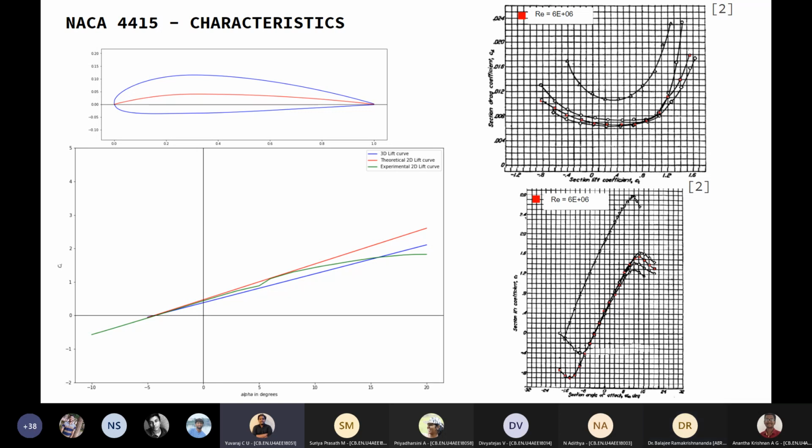Then what is the green line? Green line is that data. You don't see a kink there. Which one, sir? See, in that CL alpha curve, the green line has a small kink or something, it keeps increasing around 5 to 7 degrees. Yes. There's a sudden dip, sudden increase, then sudden decrease. It is non-linear there, correct? Yes, sir. I don't see any such non-linearity in the curve you're showing on the right-hand side. Where is it? Yes, sir. Are you plotting the right thing?